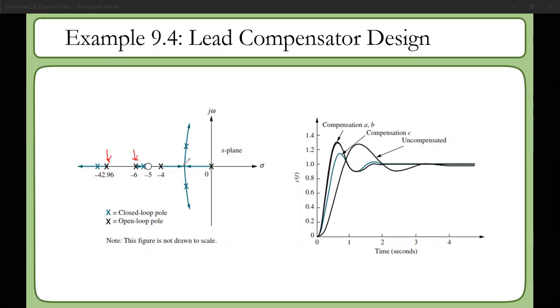Because we correspond to a particular gain value whenever we jump to that crossover location, this one is shifting there, and this one is shifting there. These two are merging, and finally one goes up and one goes down. So these are our dominant second order poles.